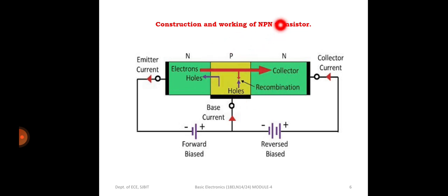No matter whatever kind of transistor it is, whether an NPN transistor or a PNP transistor, we should always remember that the emitter base junction should be forward biased and the collector base junction should be reverse biased in order to make my transistor conduct, right? Have a look at the terminals. This is my emitter part. The emitter N region is connected to the negative of the external applied voltage, and the P region is connected to the positive of the external voltage, right?